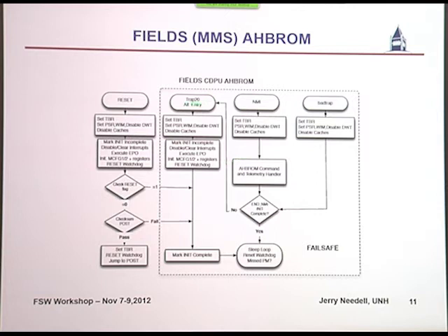And there are, again, if you're familiar with the Spark implementation, you've got this huge trap table of possible traps. We only have to populate really 3 of them. In this case, we have the command handler, so we're ready to accept commands. At this point we want to be responsive to the requirements of the command and telemetry system on the spacecraft that we're working on. So we need to be able to take commands, we need to be able to provide telemetry.